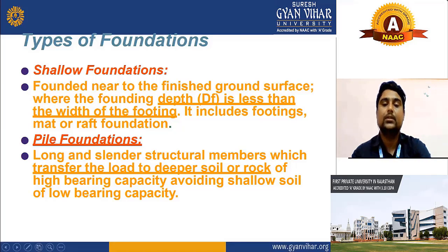A shallow foundation you can prepare only for a lightweight structure. Suppose you are going to build a 2 or 3 floor building or structure, there you can easily make a shallow foundation. If you compare the bearing capacity, the bearing capacity of pile foundation is much better than that of shallow foundation.